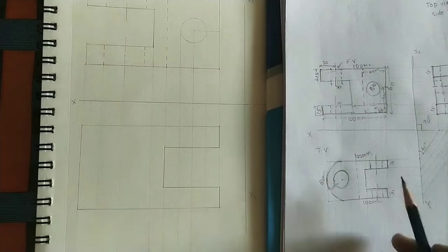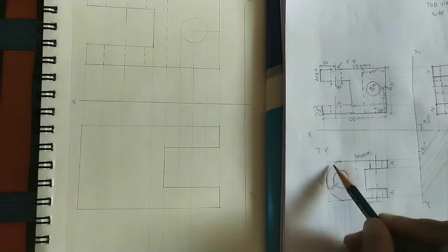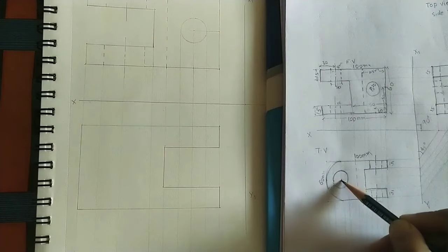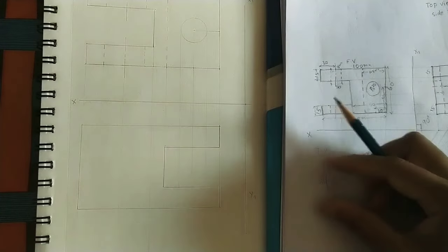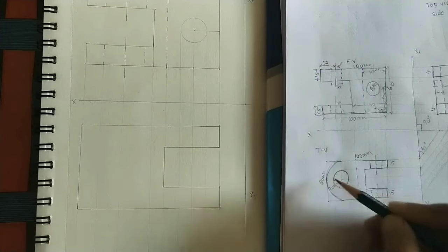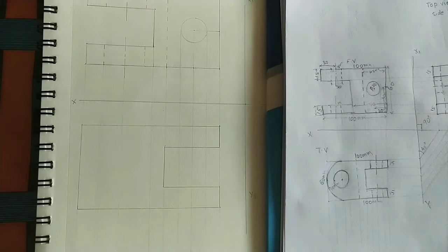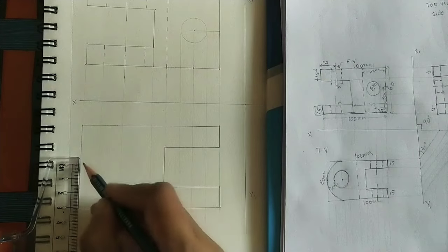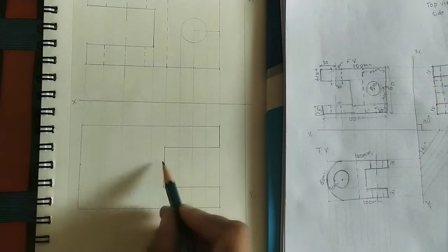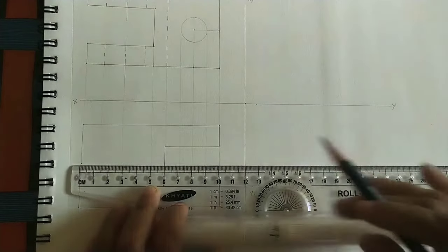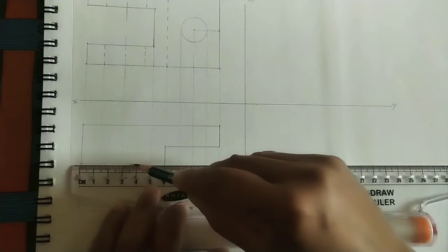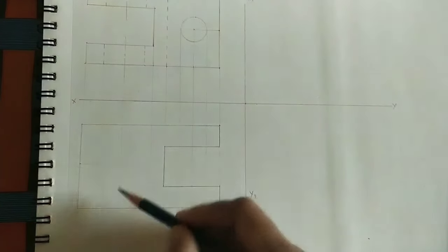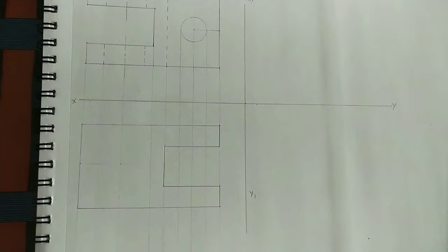After getting this U section, do these circular sections. For it, mark the center. On the axis projectile line, we have to take the center here. This is total 60 mm. Take the middle of it, 30 mm. So at 30 mm, just do one line for getting the center. So this is 30 mm. Just do one line. Now the intersection point of 30 mm and the axis line is the center for both circles.